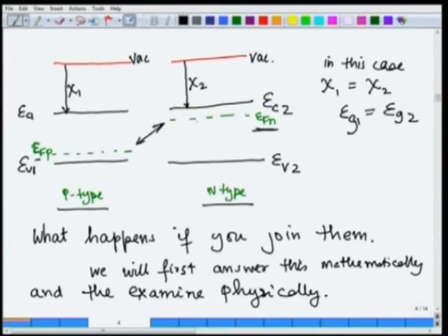of electrons on average on this side, the n side of the material, is much larger than on this side. So, clearly electrons would like to move from this side to this side, and when they do so, what will happen? This Fermi level will start going up a little bit. Remember, whenever you add electrons to the system, for example donors, then this Fermi energy starts moving up, and when you take out electrons and add holes, then this Fermi energy starts moving down.